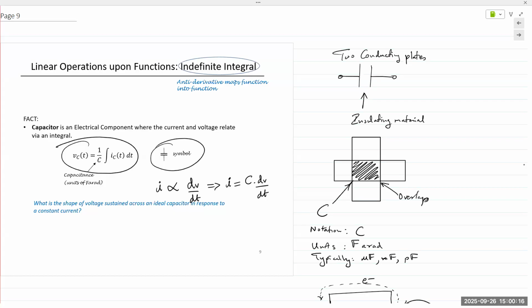Also, what it means when it's fully charged. If voltage V is a constant, meaning a DC voltage is applied, just mathematically, if V is constant, what is I? 0, right? That occurs when the capacitor reaches full charge. When Vc equals Vs, it reaches full charge. Electrons no longer flow through the circuit. The voltage across the capacitor is fully charged, but the current stops flowing. I is equal to 0. And we can see that mathematically also, right?